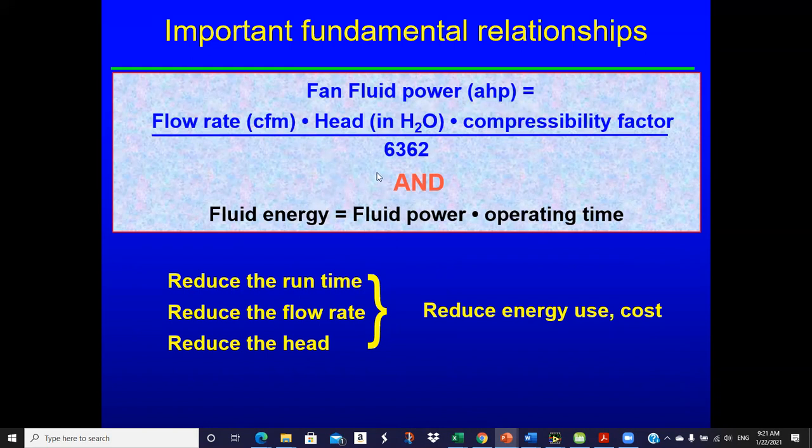Okay. And then if you want to get to input energy, you've got to start dividing by efficiencies, because that fan might be 70, 75% efficient. So then if you want to get the brake horsepower into the fan, you've got to divide by the fan efficiency. Well, then you may have a drive efficiency. So you may have a belt drive, which is 96% efficient, so you've got to divide by 96% to put the inefficiency of the belt in it.